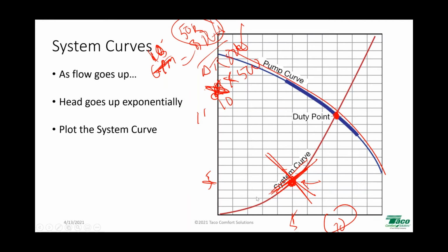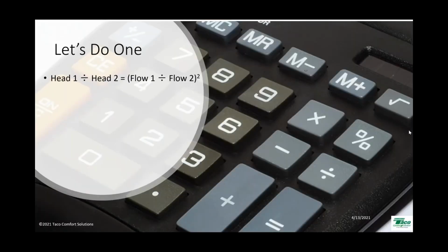All right. So that right here is a perfect picture of over pumping. So there's a math formula for plotting the system curve. Okay. I know 5 gallons a minute at 5 feet of head in this example. I know the flow and head requirements that I have. I can use those numbers to figure out the different points on my system curve plot so I can figure out where my intersection point is. Now, you may never do this math. I'll show you the math way, and then I'll show you an easy way. The math way is this.